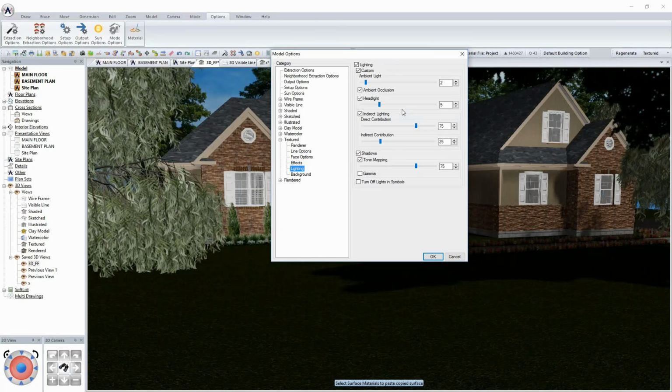So now we move on to lighting. One of the biggest things that I see with people is that the model is too dark, so what they tend to do is increase the ambient light. When you're getting towards the end of the model, I would at the very least push you away from doing that, because the ambient light is just going to artificially light the entire model.